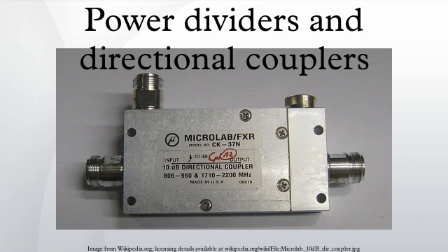The frequency range specified by manufacturers is that of the coupled line. The main line response is much wider. For instance, a coupler specified as 2 GHz might have a main line which could operate at 1 GHz. As with all distributed element circuits, the coupled response is periodic with frequency. For example, a λ/4 coupled line coupler will have responses at Nλ/4 where n is an odd integer.